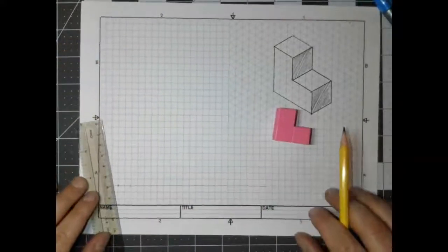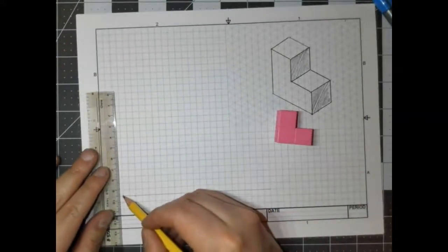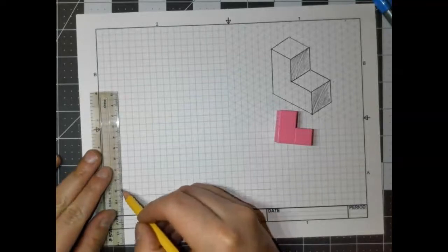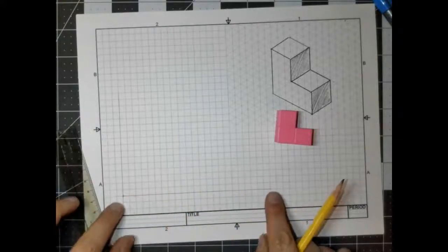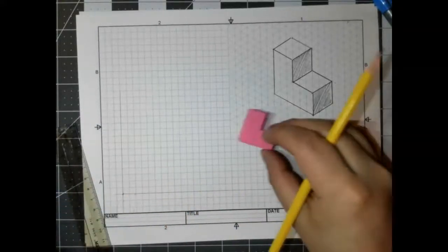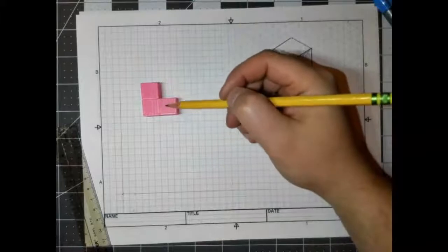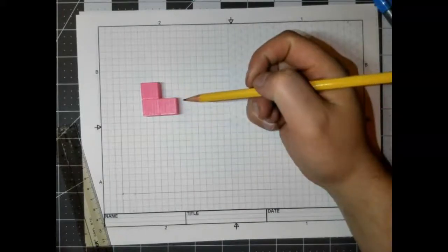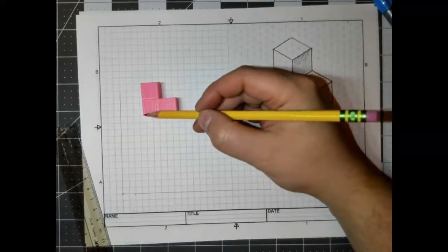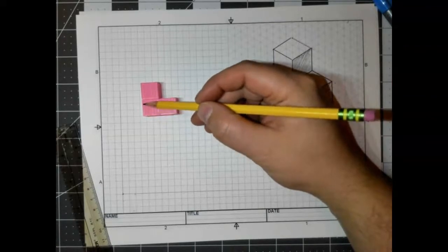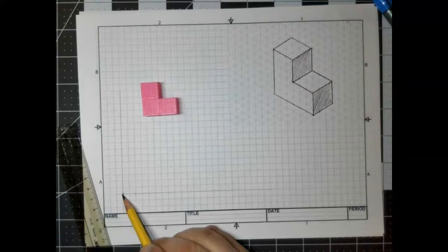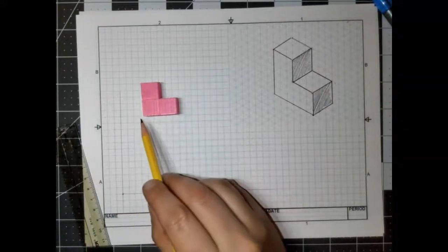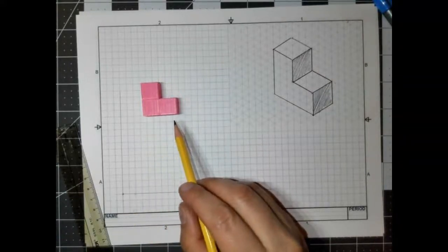And you want to do the same going vertically from that point. You're drawing directly on the grid lines, these very light construction lines. Now we said that each cube here is 3 units, so I need to go 1, 2, 3, 1, 2, 3. That's 6 units up from this corner to get the height, and then the width will also be 6.